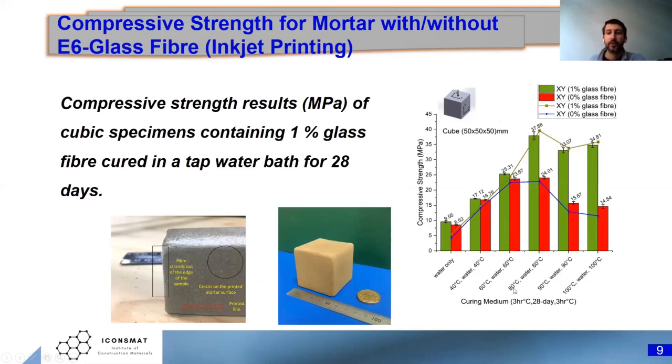After the printing process, you cure at 80 degrees, later put it in water, and later put it in an oven again at 80 degrees, and you get a very good result. This can also be done straight away, but after putting it in water you maybe will not get the result that you want. Usually we know compressive strength is pretty crucial for construction purposes.